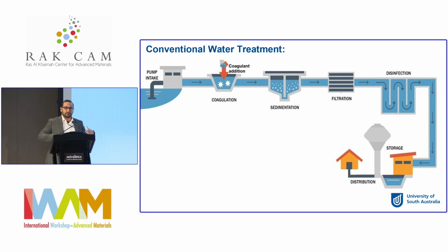During such an event, when the organics loading is high, the current practice is to put in powdered activated carbon at the beginning and then remove it later in the separation process. In addition to the additional cost, the sludge or waste from the treatment plant also increases, and they use more chemicals to improve the separation process after using the powdered activated carbon.